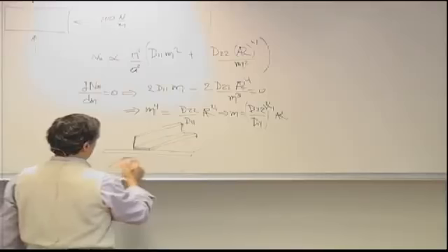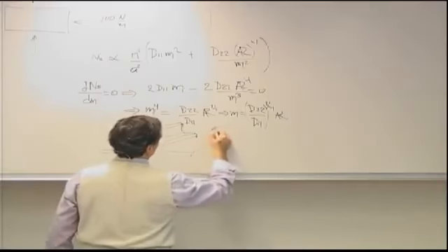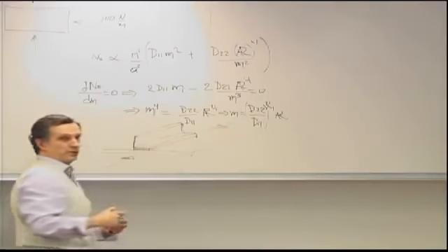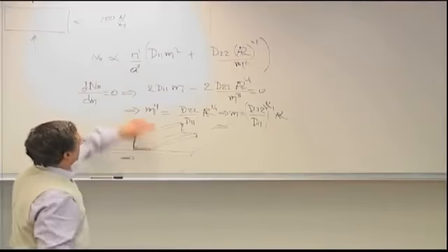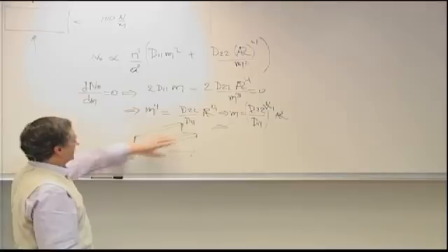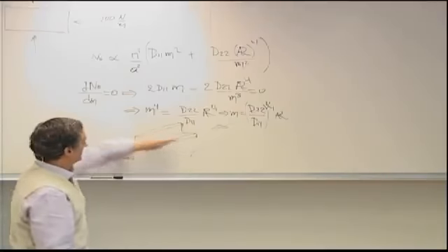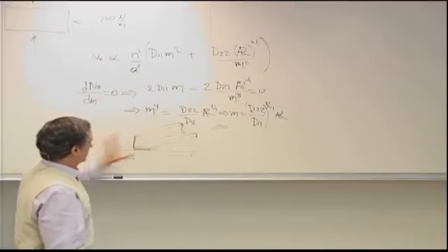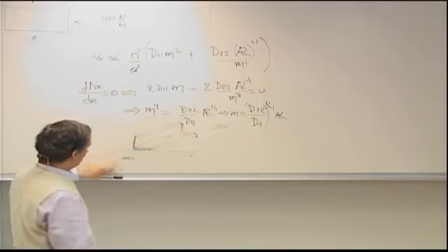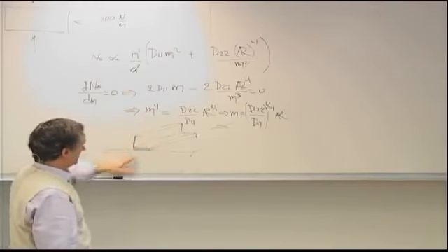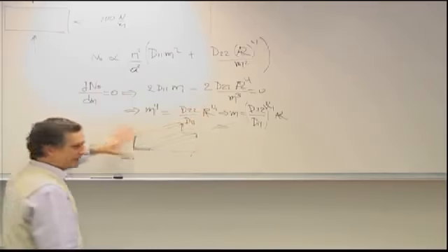And this whole thing might be under compression, which means some of the compression load goes into the skin, some of the compression load goes into the stiffener, and we'll find all kinds of ways of doing that. What's important is if you look at each of the flanges of this stiffener, the whole stiffener is under a compressive load at its neutral axis. That is after the Saint-Venant effects of loading introduced into the stiffener have died away.